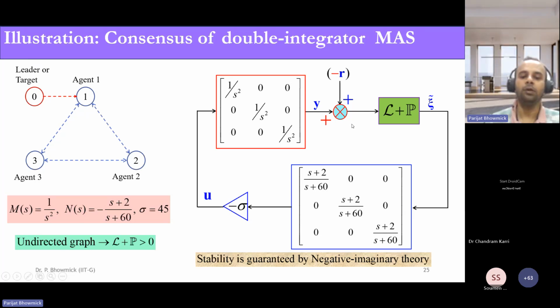So even if E equals 0, what will happen? R plus Y will be equal to 0, so Y will be equal to minus R as t tends to infinity. Even if everything works fine, the output will reach the minus of the reference. That is the reason why you have to deliberately negate the reference signal, and then the proper true tracking will take place. That is the only matter of concern here.